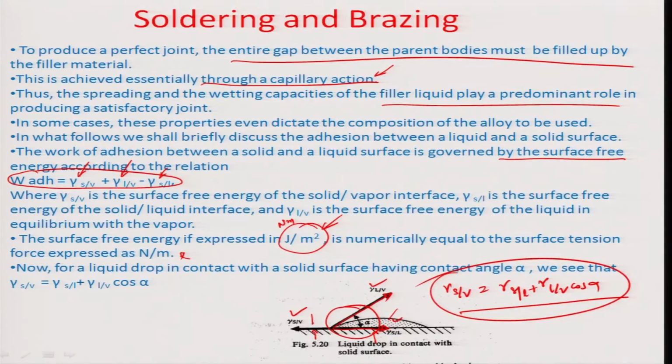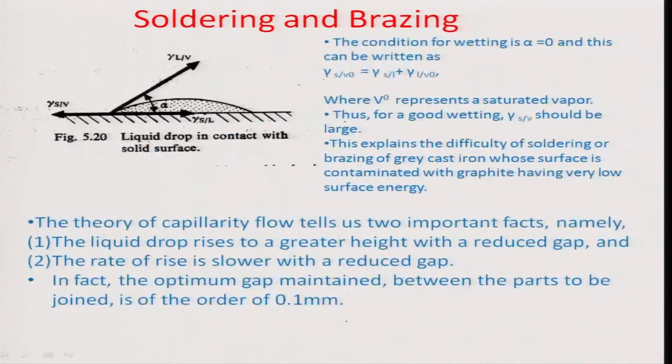the larger this contact angle alpha is, the lesser wetting property the fluid will have on the particular surface, and it may not be a very conducive situation for creating a good weldment or a good solder or a good brazed sample here.